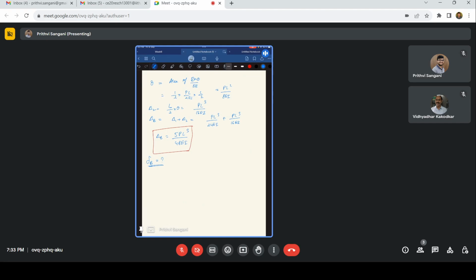That's what it is. The same thing, you divide the whole thing by EI, and you integrate it from 0 to 9, the length of the beam or the length of the span AB. So this turns out to be 243 by EI, 243 by EI into VC, because this VC is unknown.